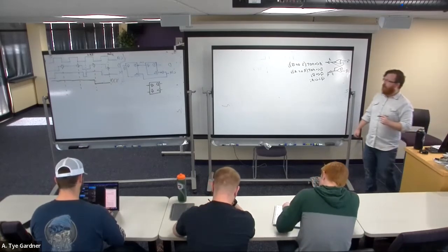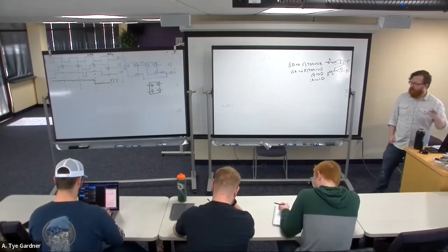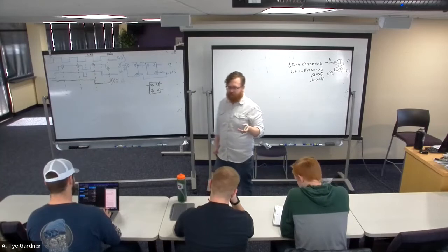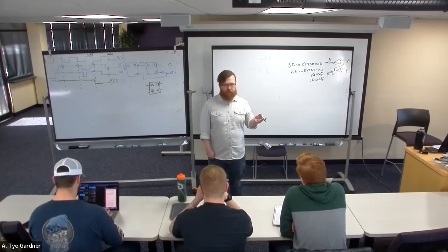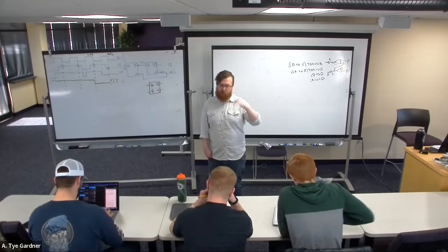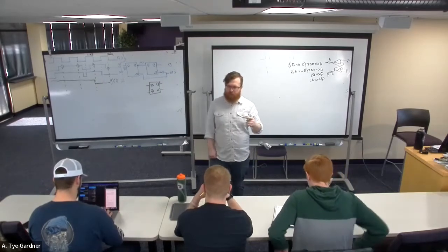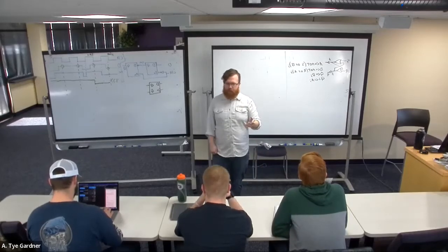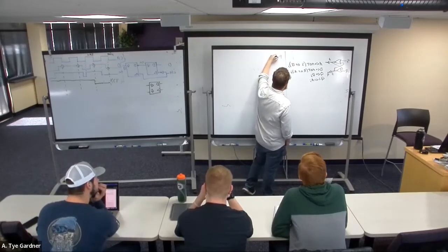Q sub B. Okay, so now we want to design something a little bit better, right? We want better code than that. And so let's talk about how we design a flip-flop, D flip-flop, let's say. Remember how we've used processes in our test benches before? A process says that this portion of code is sequential logic. It happens in order. So we're going to start using processes inside of our design, not just in our test bench, and this happens just like in the test bench, inside of the architecture's begin.